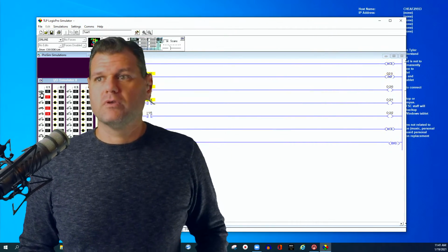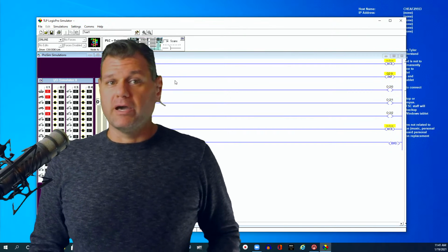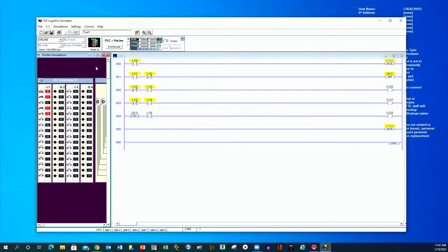Okay, but something that is happening is that my rung 1 is jumping over all these logics. So as you see, this is active, and these are true. So normally you'd have a true state. But for that reason, it's not doing it. So let me turn this off. Let me switch that. Okay. Now the jump has gone away, and see what happened? These all came on. So let me do it one more time. I'm going to hold it down.